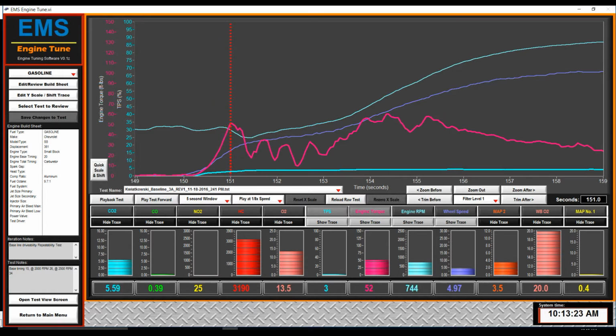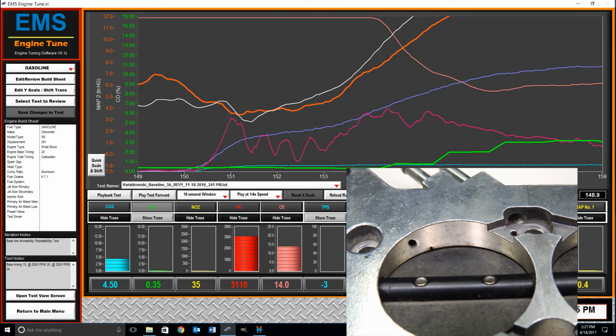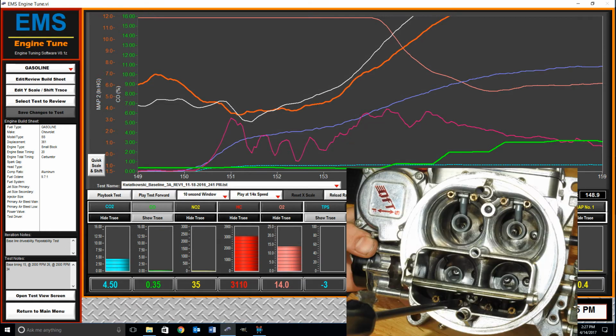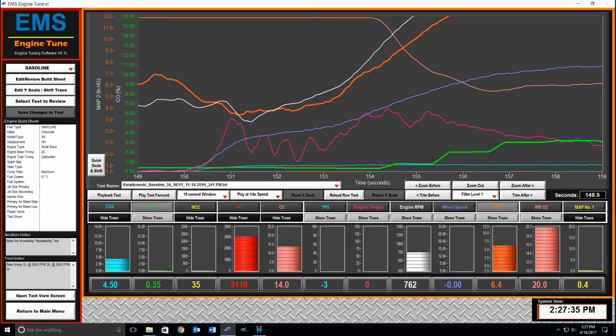On a carbureted car, we use a circuit called the slot. That is the idle to main jet transition circuit. This circuit is governed by air bleeds. The air bleeds assist us in getting the correct air-fuel mixture for this transition.